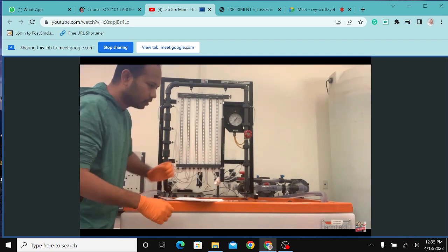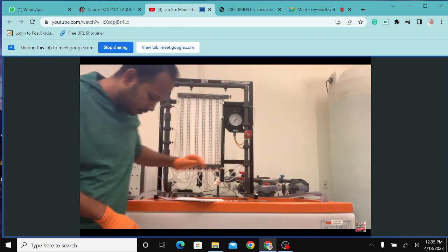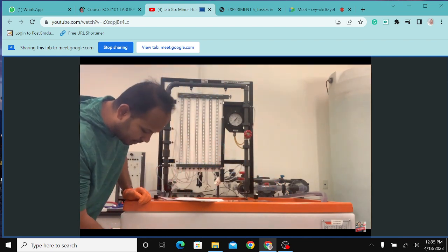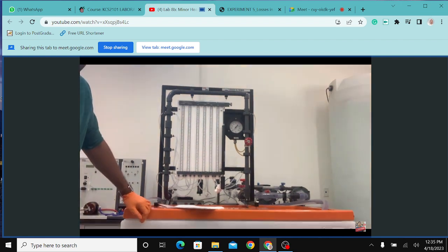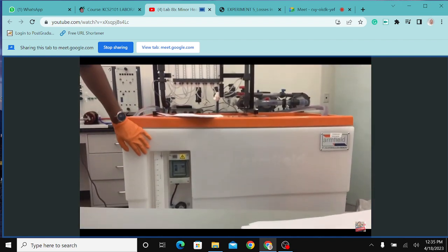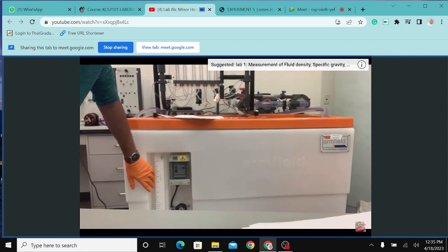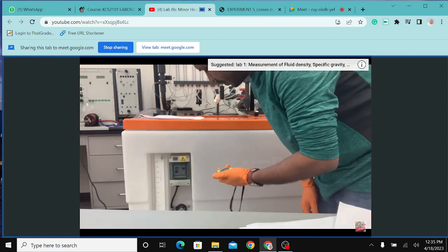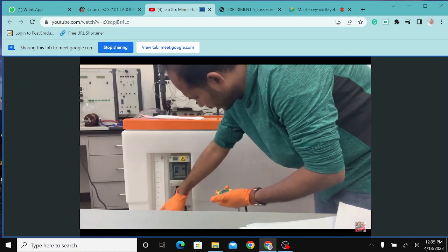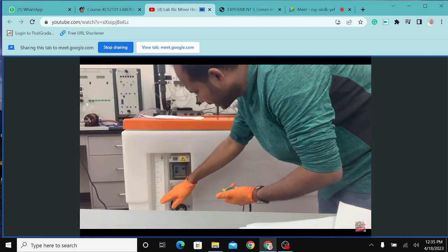So I'm going to lock this outflow. Now water is going to go high up on this meter in your bench valve here. I'm going to use this reading with a time. So I'm going to measure how much water filled up in a given time, and I can measure the flow rate. The pump is running, the water is going up. My goal is to have no more than 70 liters per minute.